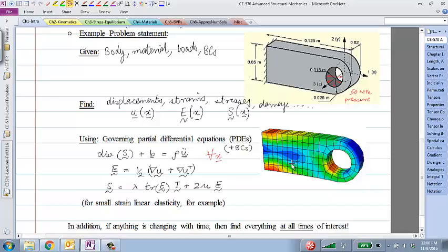If you keep using smaller and smaller finite elements, lots and lots of divisions, you will actually approach the exact solution to this problem in the limit of mesh refinement, where the element size goes to 0. So if it's a well-posed problem, if it's a solid material, this computer simulation has the potential to give you almost an exact solution to it.